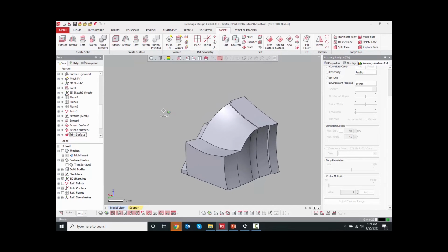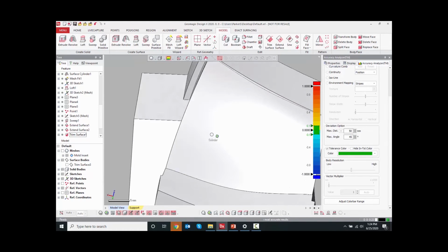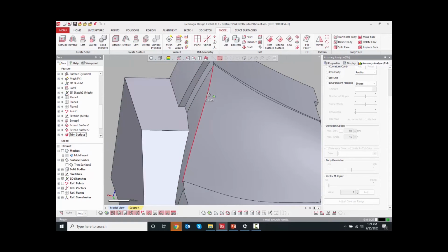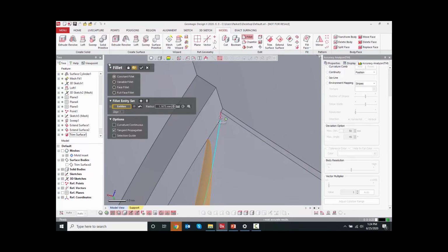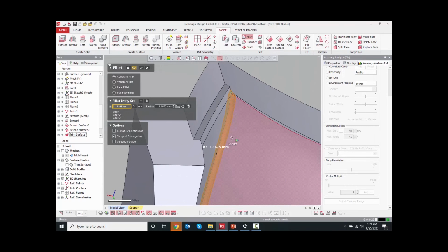Now it's really just a case of adding some details here. Like I know that I'm going to have some deviation in these areas because I've got some fillets there that I need to model. Very simple to do that. Actually, really nice to have a mesh as a guide in this case because I can choose to fillet that edge, and actually I'll choose these two as well. And I'll let the software estimate the radius of the fillet from the scan data. So essentially along that edge path there, it'll cross-section the scan data in a number of places and average out what it finds to be the fillet radius when I use this estimate command.